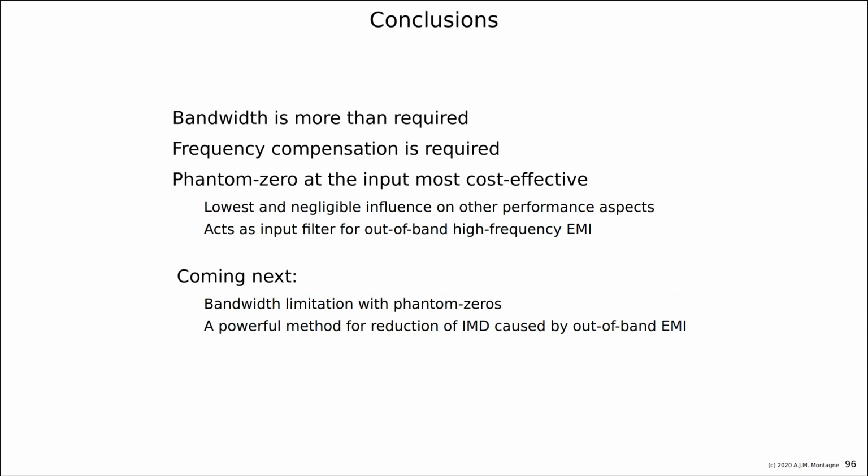For example, consider that I am making an amplifier, a unity gain voltage amplifier, and my controller would be an op-amp with almost zero output impedance. Then any load impedance does not put an attenuation in the loop.